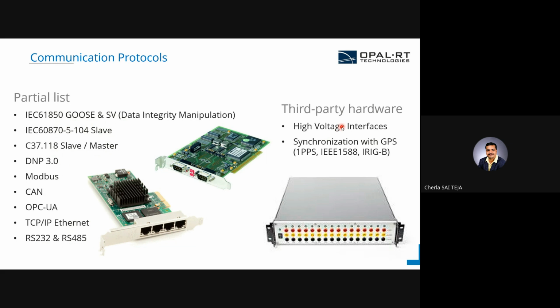And we have some third-party hardware as well. Whenever you are having these smart devices, you need to have that data transfer synchronized with a reference clock. So we can have a reference clock with the IRIG-B format or 1 PPS signal or IEEE 1588 based format. So as I told, our solution is flexible. Depending on the requirement of the user, we can configure and send and receive data in all these different protocols.